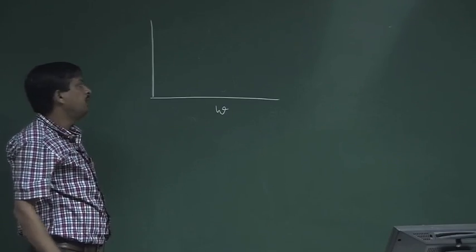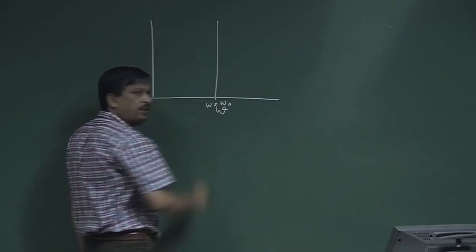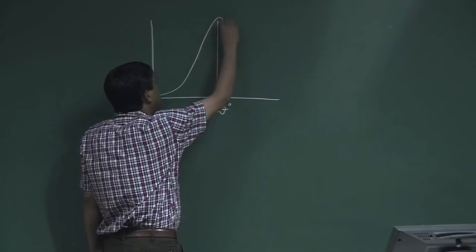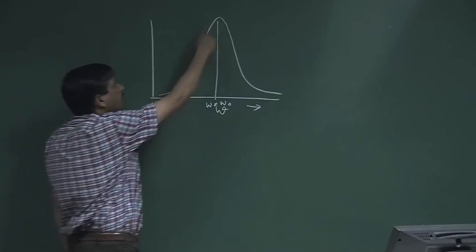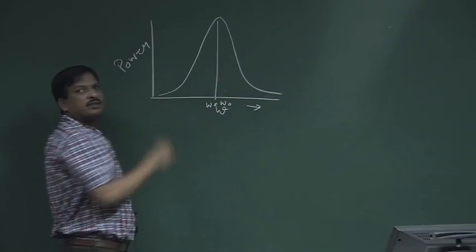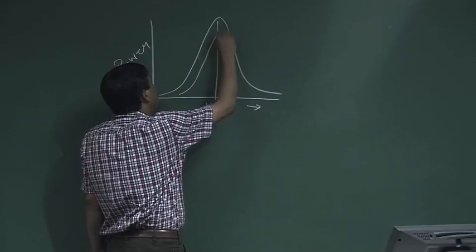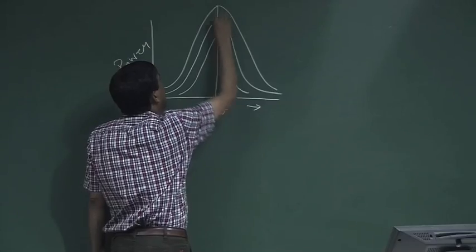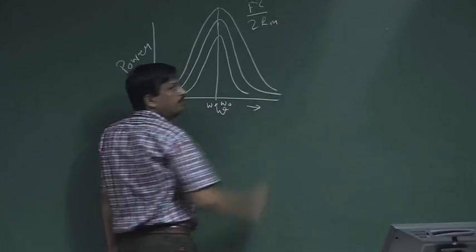The maximum power will happen at omega equal to omega 0, and on either side of omega 0 I get this kind of curve. This is called the mechanical resonance curve. Different kinds of resonance curves can be obtained. So, the maximum power is F squared by 2 R_m.